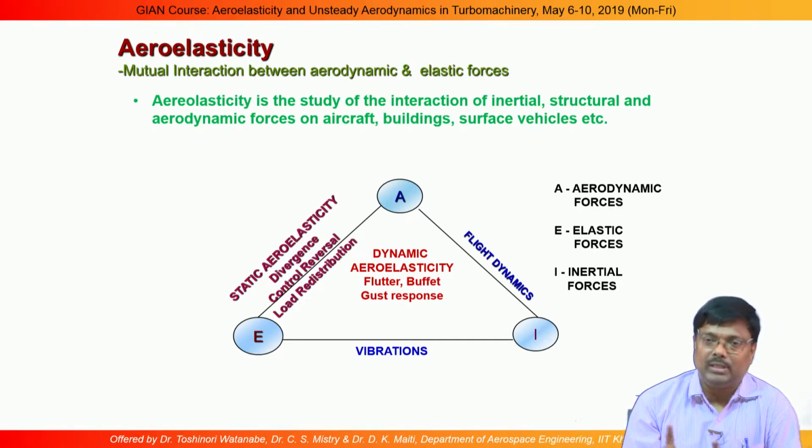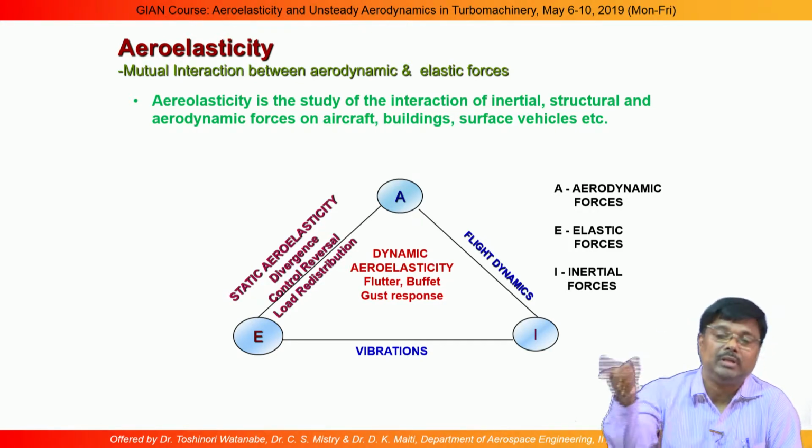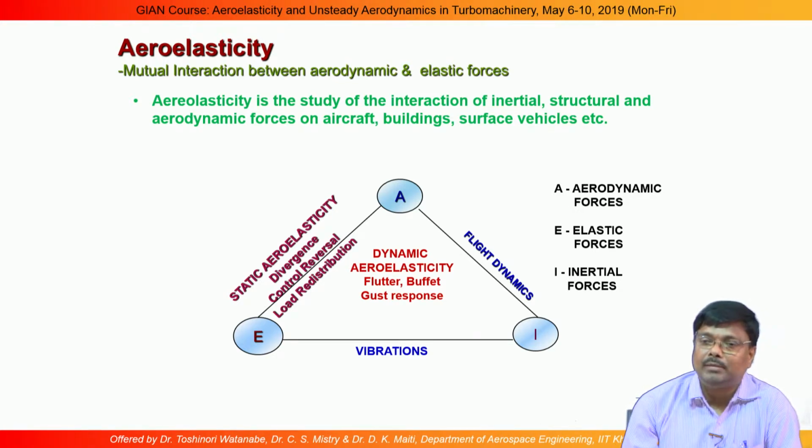So when both together are satisfied, then we can say this is okay, the aircraft can fly. But measurement of damping is possible only when you are in flight. Before flight, in the design stage, we do not have any estimate of damping, because we cannot make a mathematical model for damping, it is very difficult. We can make a mathematical model for elasticity and for mass, but not for damping. What we can do is assume some damping and proceed with that.